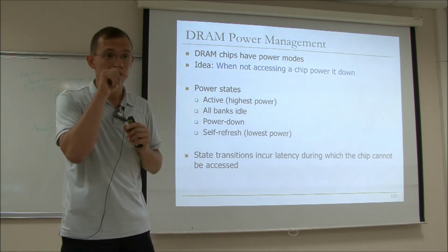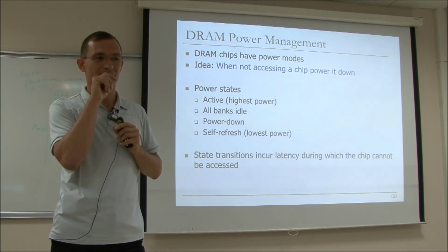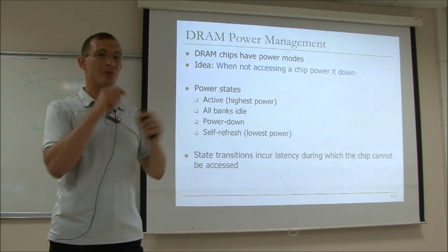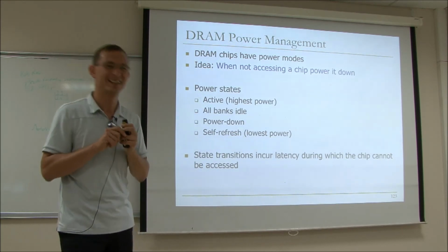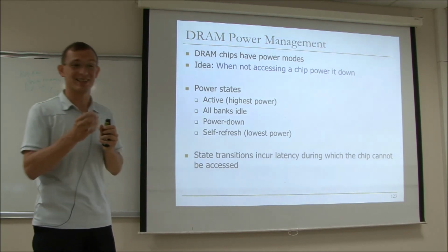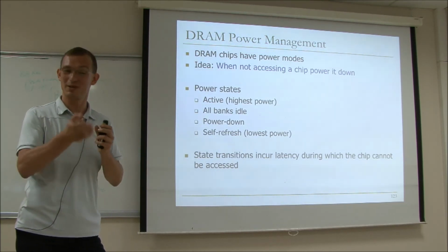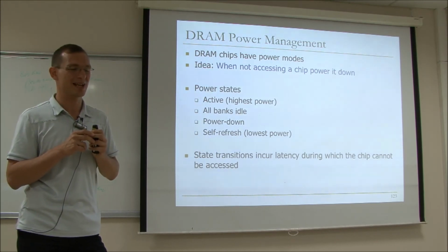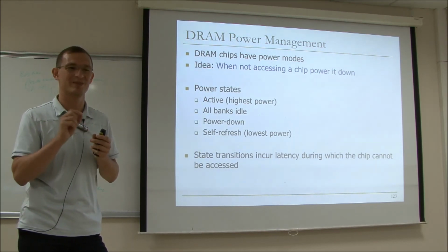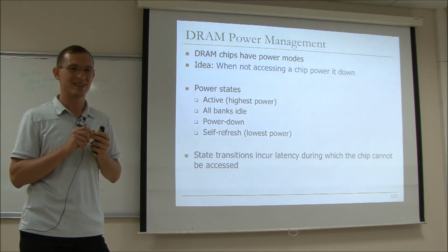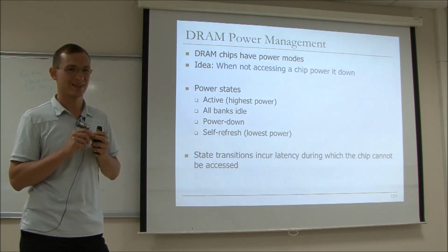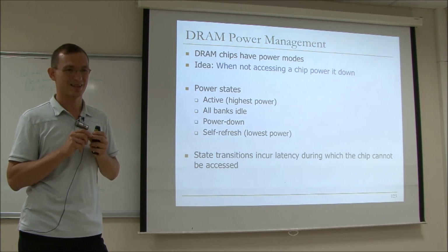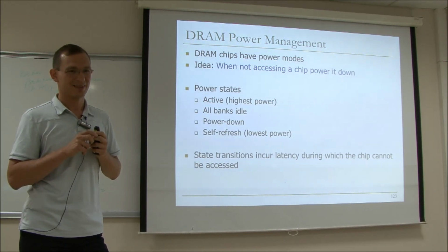Dual row buffer implementation, are there any commercial examples of that? Of multiple row buffers? Dual, at least. So that's a good question. I believe Hitachi tried it in the 1990s, and Toshiba also proposed it. They looked at these multiple row buffers, but cost per bit was so dominant at that time. A bit more residence in the row buffer may result in more hits on that, but in the meantime, you're delaying some other things that will come into that row buffer. Of course, there's a trade-off there.